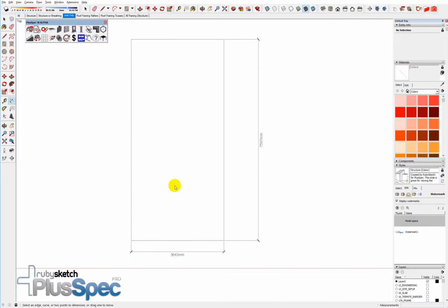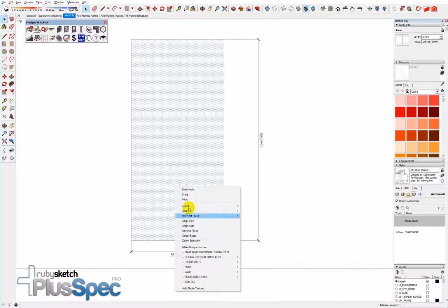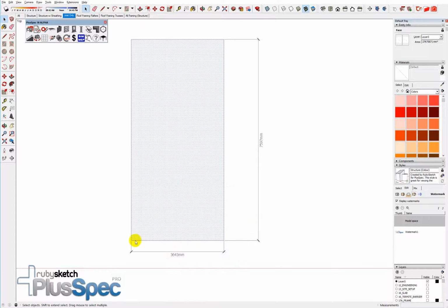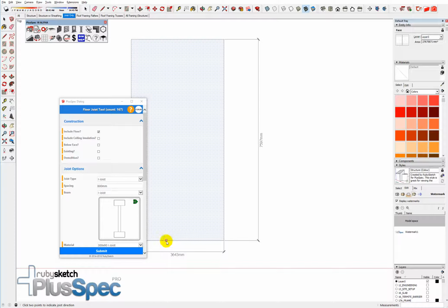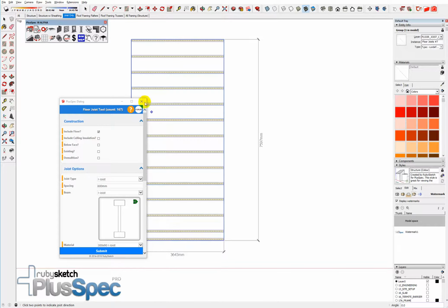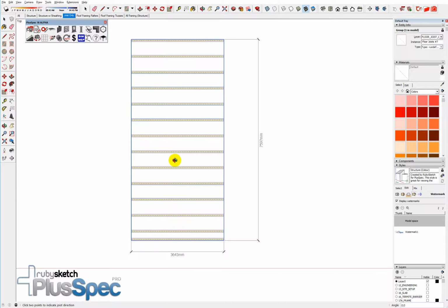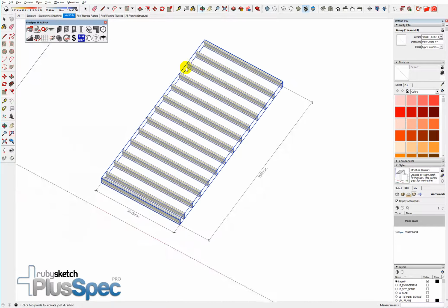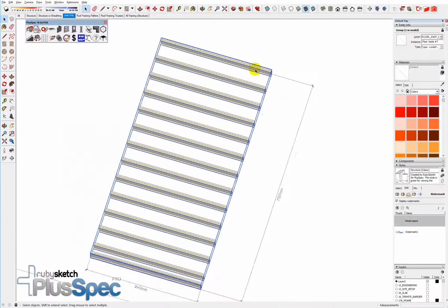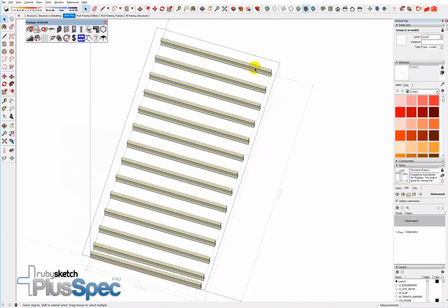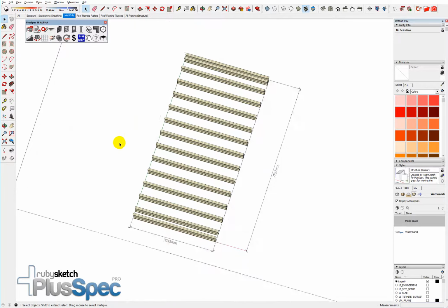Okay. If I select this rectangle here and go to my joist, just about anyone can figure out how to do this. It's basically divide the length by the width and so on. I'm just going to put in some joists here. Okay, and it was reasonably simple. My joist is spaced out there. If I decided that I wanted to have a double joist, I'd simply click in here and put a double joist in. Okay, right, very easy example.